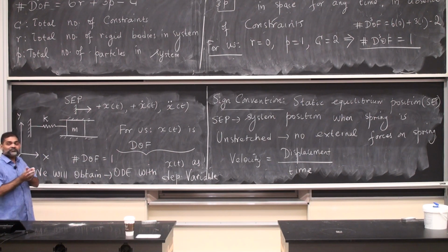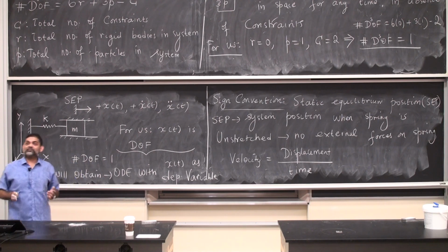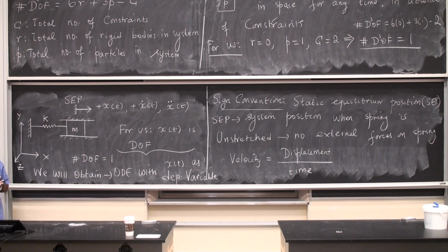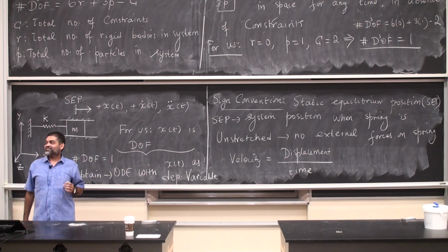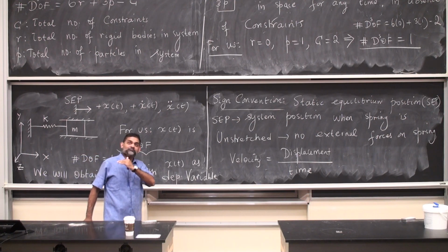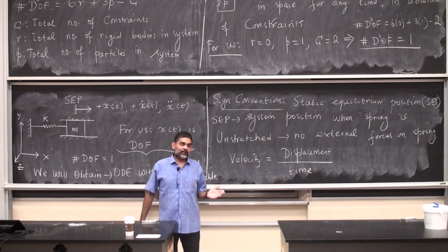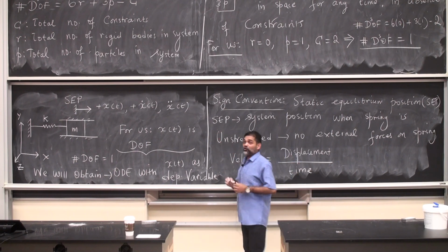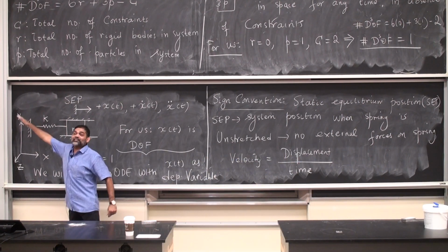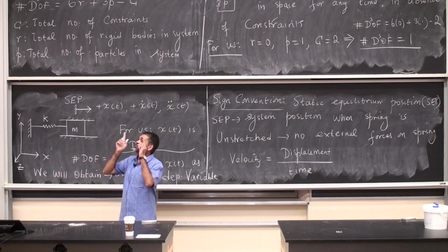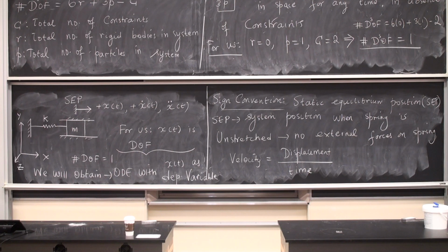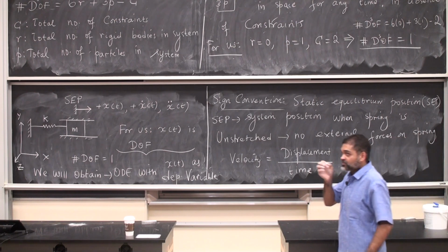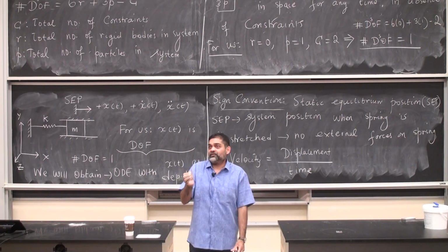Once we are done with all this, whatever force acts on this mass will be taken to be positive if it is along the positive displacement direction. If it is pointing opposite to it, it will be taken negative. And tomorrow I can come and tell you that all of this is wrong. I am going to choose the direction pointing to the left as the positive displacement, and my answer should not change. The physics of the problem cannot change based on where you get up in your home. This is just a sign convention. It's a road map. It does not change where you end up.